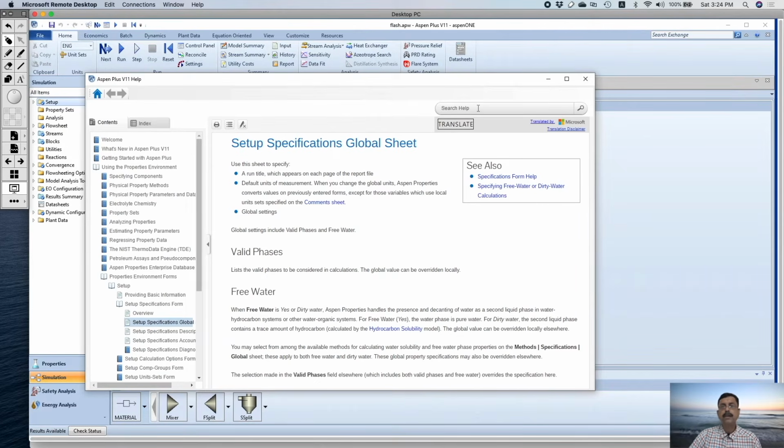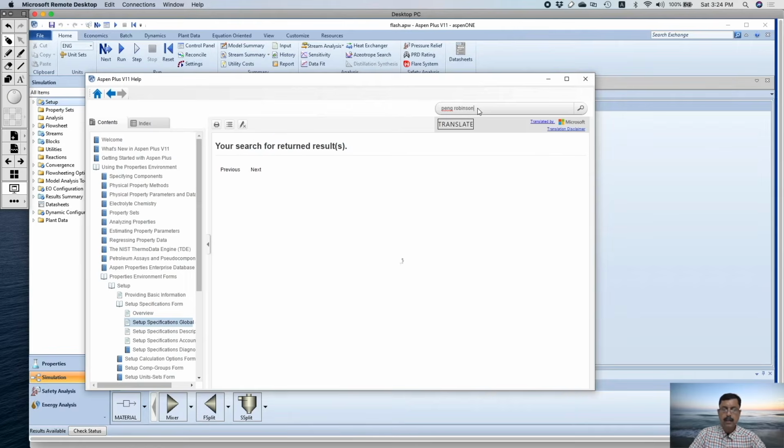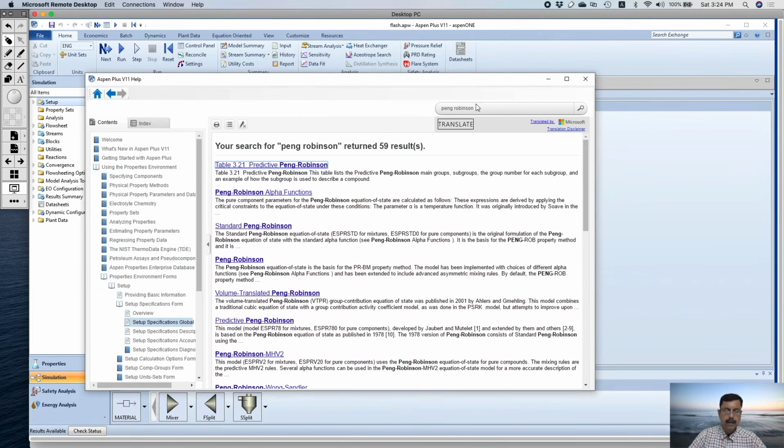If you click here, you will get help, ready help. For instance, if you want to know about some thermodynamic model, say Peng-Robinson, you write Peng-Robinson, then it will search, and there are 59 results.